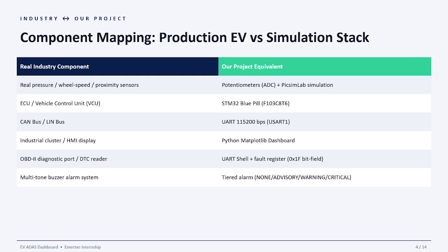The fifth phase implemented the ADAS system using three HC-SR04 ultrasonic sensors. This module provides forward collision warning, blind spot detection, parking assist, and time to collision calculations. The sixth phase added the fault detection and alarm systems. It continuously checked for abnormal situations like overheating, critical battery, low battery, collision, sensor failure, and communication failure.